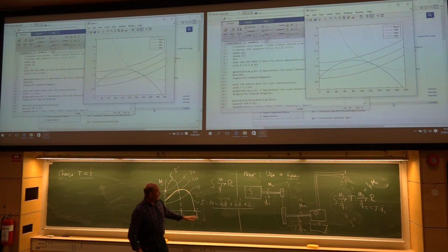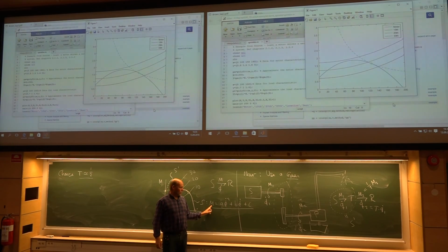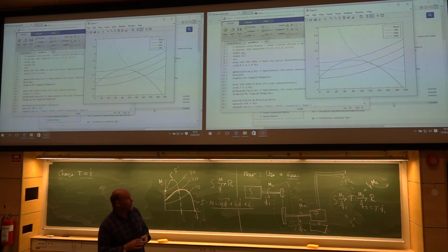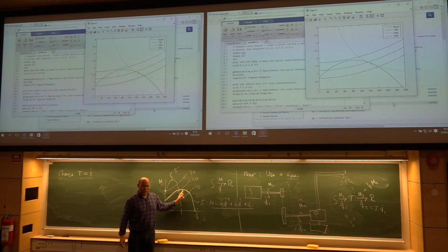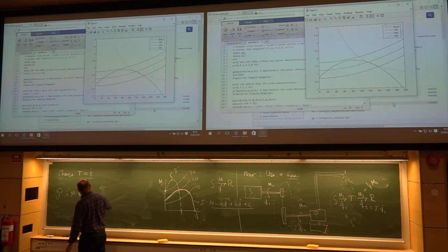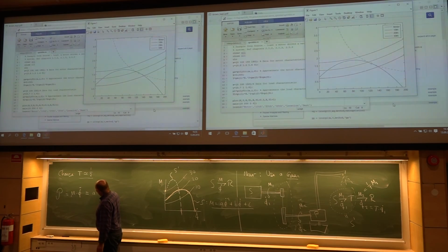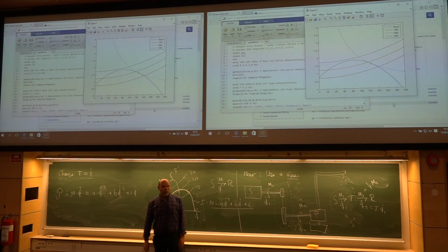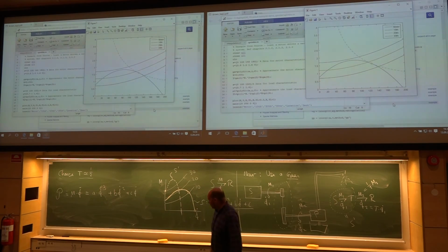Now you have an analytical expression for this torque. Then it's fairly easy to go further. You can have an analytical expression for, say, finding the maximum power here. What was the maximum power? Power equals torque times rotational speed, which now will be A multiplied with phi dot power 3 plus B phi dot power 2 plus C phi dot. So there you have the function for the power.